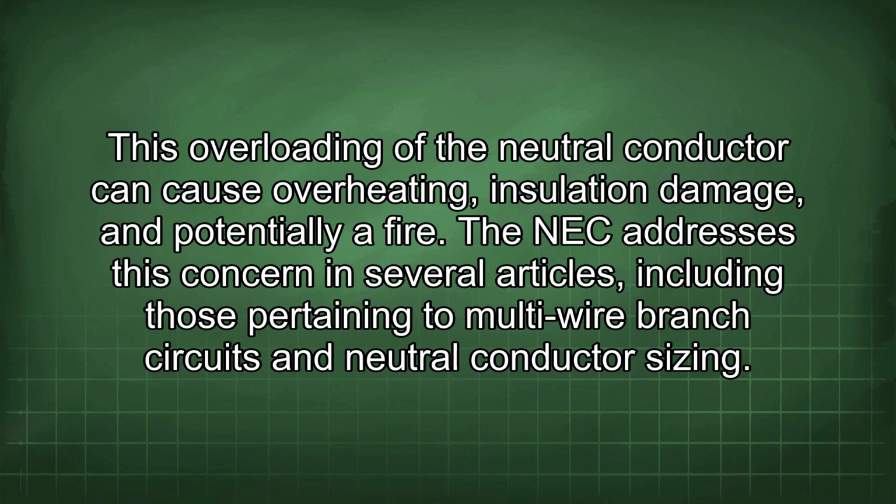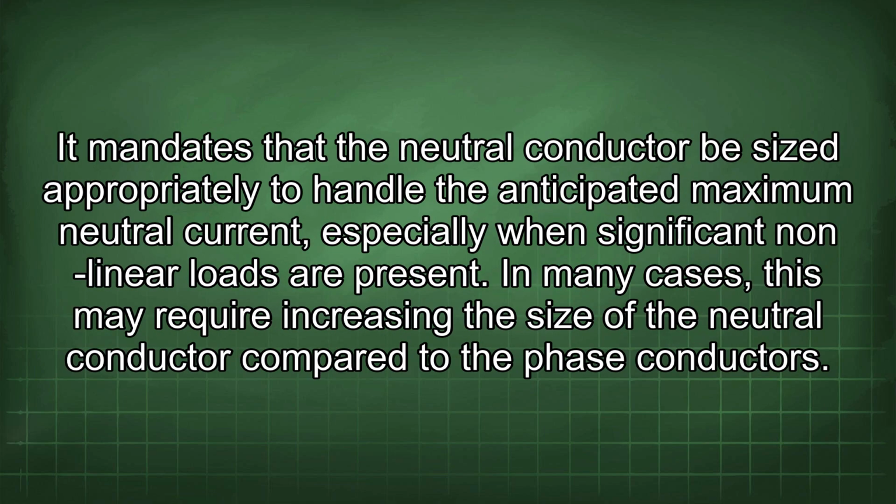The NEC addresses this concern in several articles, including those pertaining to multi-wire branch circuits and neutral conductor sizing. It mandates that the neutral conductor be sized appropriately to handle the anticipated maximum neutral current, especially when significant nonlinear loads are present. In many cases, this may require increasing the size of the neutral conductor compared to the phase conductors.